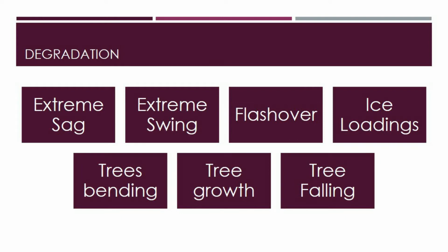extremes is extreme swings of the power line, which occur when winds force conductor and insulator movements up or down or even sideways. Another extreme is the highest flashover voltages, which occur when conductors carry lightning surge currents that can damage trees or other nearby objects by causing voltage breakdown. A fourth one is an extreme of snow or ice loading in some seasonal conditions, which causes the anticipated sag of tree branches to fall into lines.